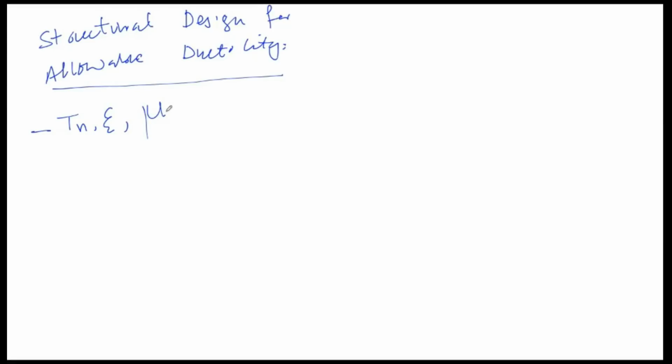The design yield strength and design deformation for an SDF system can be determined from the inelastic design spectrum. If you have these, you can obtain the yield strength and you can obtain the design level deformation, uy, using the inelastic design spectrum that we just saw.